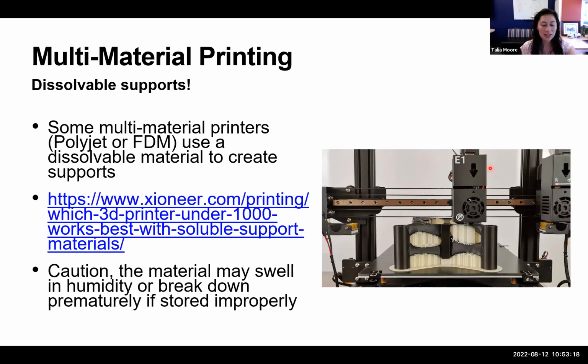I highly recommend, if you want to do this, going to this link, because it takes you through all of the different ways that you can create dissolvable supports, all of the different technologies and the pros and cons of each. It's extremely thorough. I just want to caution you that the material used to create these dissolvable supports may swell in humidity, or it might break down prematurely if you're not storing it properly. So just make sure that you don't buy tons and tons of it and then don't use it for 3 years. That's not going to work out well.